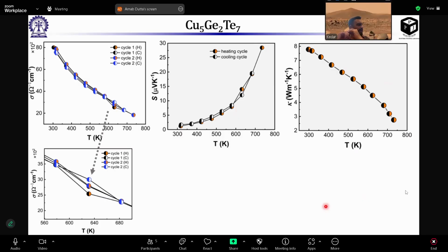One thing to check also is that there will be an amorphous limit, right? Which is a simple calculation. Do you know the amorphous limit of thermal conductivity for this material? It's where there is no crystal structure, you just take the atoms together. There's a simple formula for it based on the specific heat. So you just calculate that amorphous limit. Usually it's pretty small, like 0.2 to 0.5, something like this.